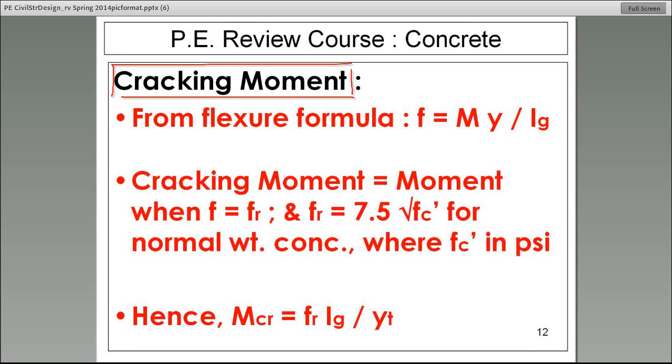And if you go back to the notes that I presented to you last Thursday, what equation did I give you for bending stress? Do you remember the equation for bending stress? What I gave you last Thursday was sigma is equal to Mc over I.